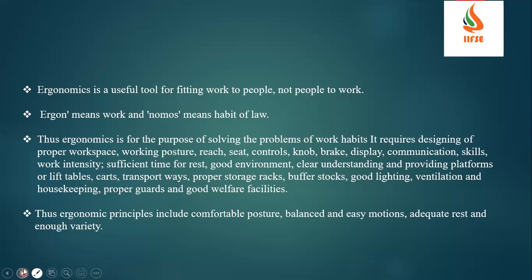It means they are giving a renovation in the machining process or stitching process. For example, in the automobile industry, before they used to tighten manually. Now pneumatic wrenches have come, so that they avoid the frequent wrist movement of the operator. So this fits the work to the people, not the people to the work. With an ergonomic study, we can help the operator avoid strain, and he can complete his job effectively and more efficiently.